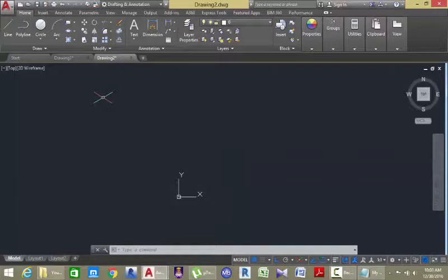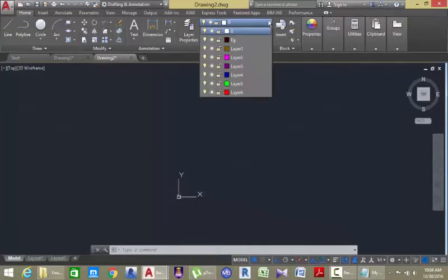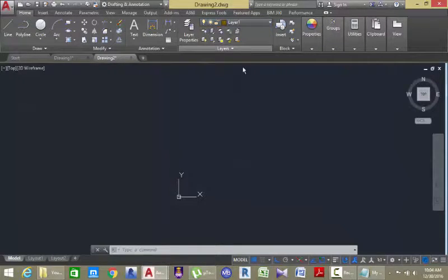We're going to draw a table 60 by 30 by 30 units. So normally when I draw in isometric mode, sometimes I prefer to draw everything in the top plan, then I can move them afterwards and also use them as a reference when I need them. So go to the home tab, layer panel, and click the down arrow. Select the layer 1 option.